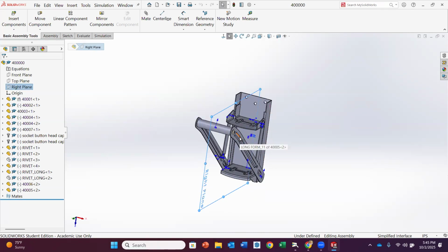Because I have that plane of symmetry in my assembly, when I did each one of my parts, they all have that right plane going right down the middle, and all the parts are symmetrical. So when I brought them in, I could line up that center plane on my assembly and on the individual parts. That's one of the mates for every single thing that I have.